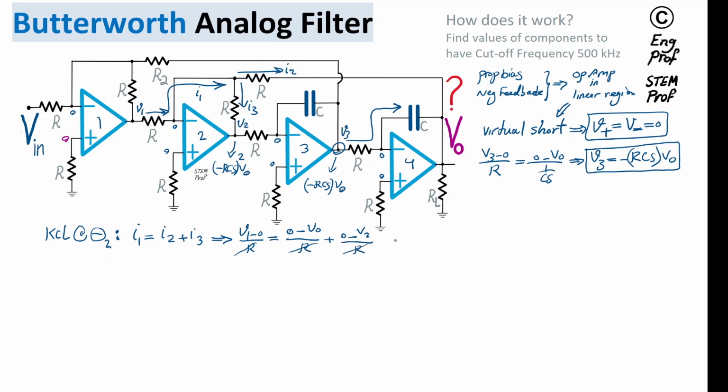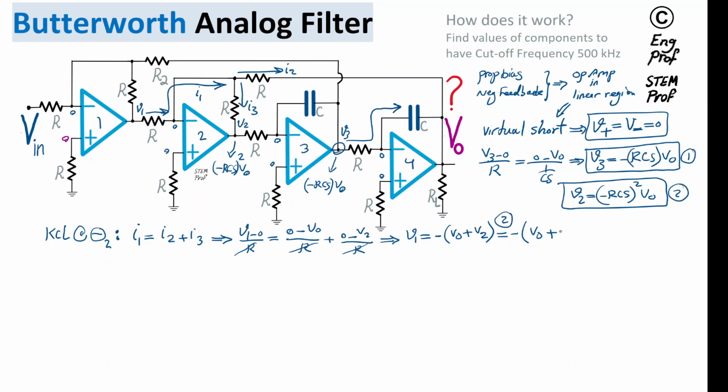resistor R. These resistors R cancel out from both sides, and I get V1 is simply minus Vout plus V2, which I can then substitute for. So it's equal to minus Vout, and then for V2 I'm going to substitute from what I found here. So let me write it here as well. V2 is equal to minus RCS squared Vout. So that is equation number, let's say 1, 2, and I'm using equation 2 here. So it's basically just R squared, C squared, S squared, and I can factor out Vout. So I found V1 as a function of Vout. Let's refer to this as equation number 3.